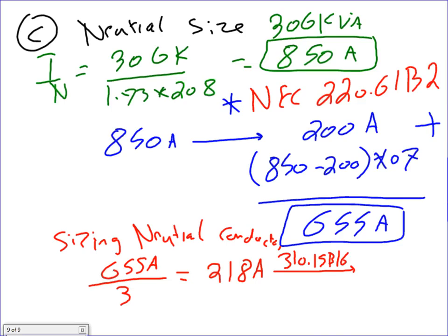Take this to 310.15(B)(16) under which column? The 75-degree column. I hope you didn't forget that 75-degree column. What do we have? One conductor for 4/0. Then we're going to run into a problem with the grounding, so we have to go up, with a grounding electrode conductor. We'll check that one later. Any questions about the 4/0? So far, we have our sizes at 4/0.